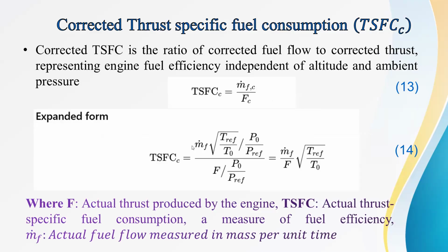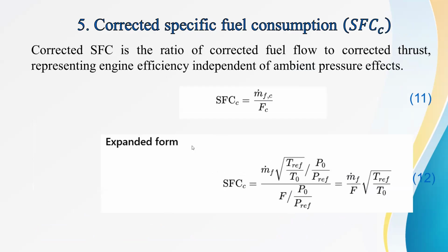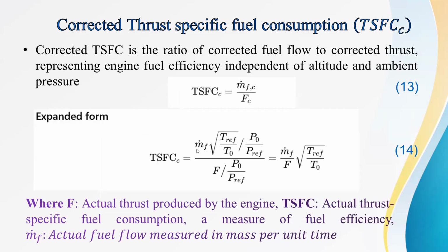Then we have thrust-specific fuel consumption. Specific fuel consumption is different from thrust-specific fuel consumption, though in some cases they are the same. For jet aircraft, we use thrust-specific fuel consumption. It is brake power specific fuel consumption for reciprocating engines or propeller-driven aircraft. But for jet aircraft, we use thrust-specific because our